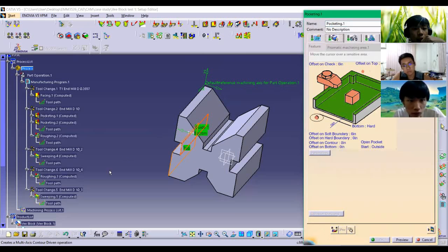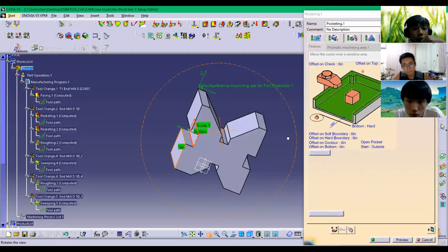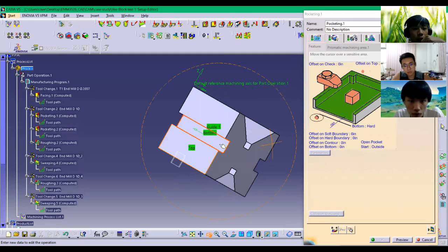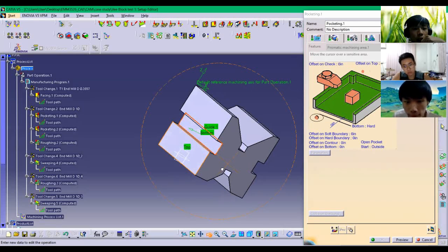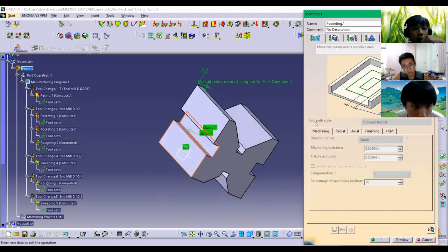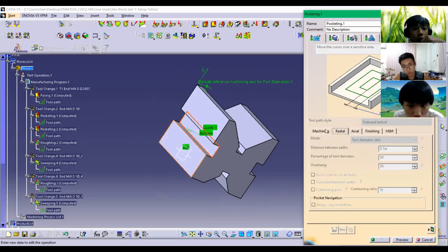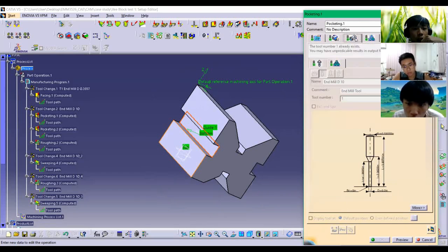First we have to select the bottom of the surface, then we select the top as the part. Then you can proceed with selecting the bar side. It's still the same. This time we select the outward highlights, and the other settings remain the same. For the tool part we change the dimension to 0.2 inches.